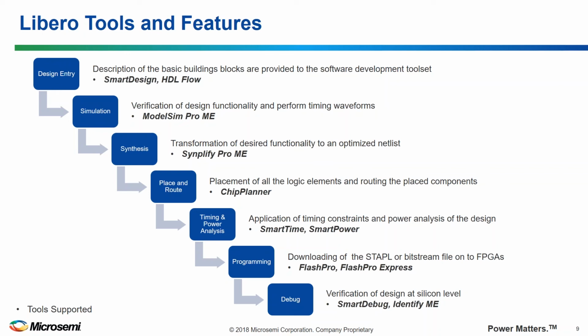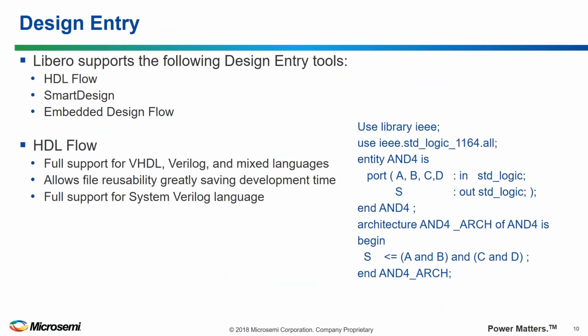And then finally, we provide the programming files and the programming tools so that you can program the devices. And then we can move on to the debugging stage, and we can take advantage of a Microsemi tool that I'll introduce you to that's called SmartDebug. And we also include another Synopsys tool called Identify ME that allows you to debug your design.